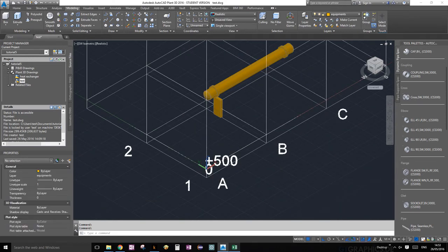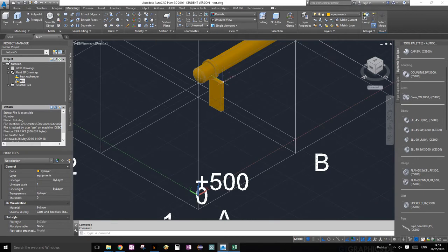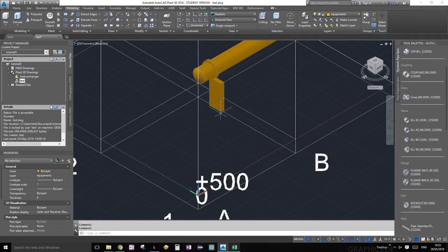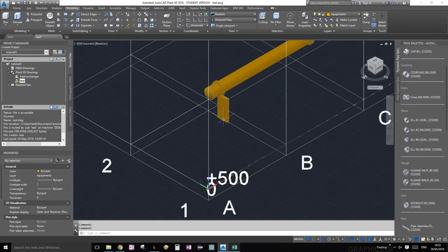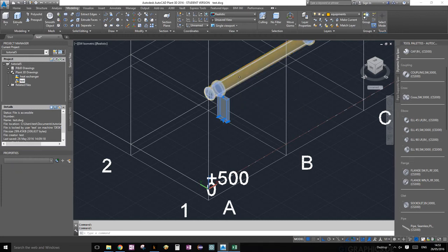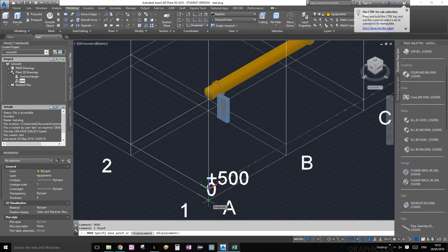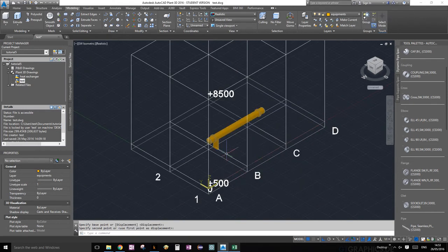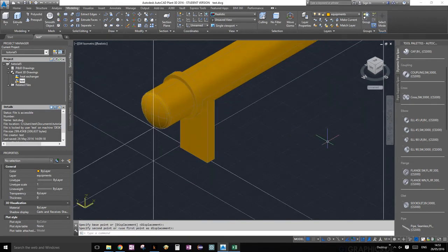See, for some reason, I don't know why, sometimes it works for me, sometimes it doesn't. AutoCAD drew my little box with the bottom actually at the very bottom surface of our grid, which is so stupid. Fixing this is very easy. Select your box, start typing move, select a reference point. We're going to select the very bottom point and then snap it onto the top one, and done. And see, this is what I want it to look like.